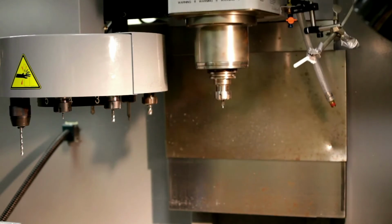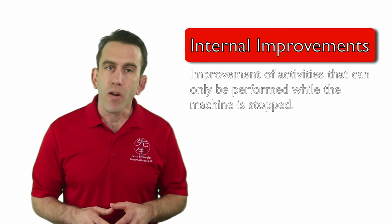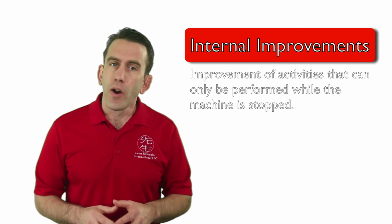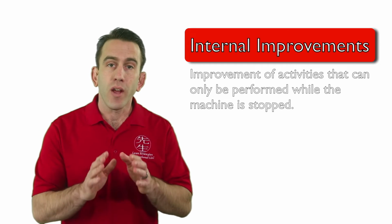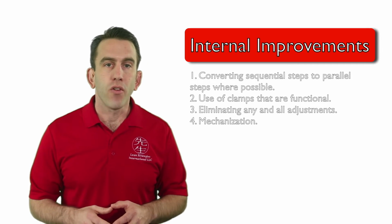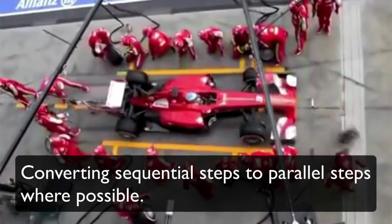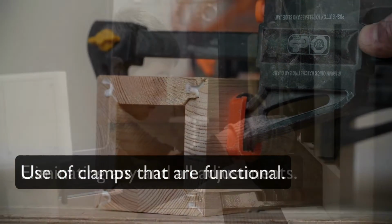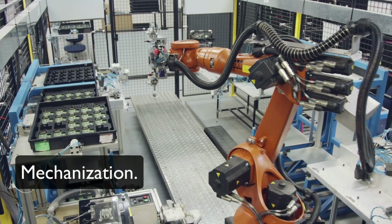This can be a bit more tricky than improving external setup activities and oftentimes requires engineering assistance, investments, and a little bit of planning. Nonetheless, there are some things that you can do which will bring your times into the single-digit time frame. The four techniques that can further reduce your setup or changeover times are: first, converting sequential steps to parallel steps where possible. Second, use of clamps that are functional. Third, eliminating any and all adjustments, and last but not least, mechanization.